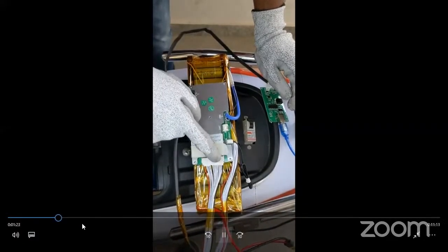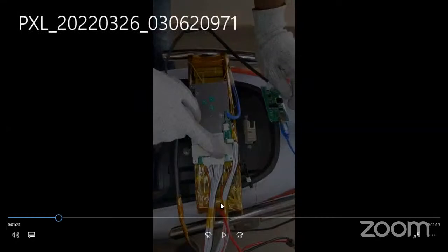It starts from the negative wire. So I'll just take a glance again. You can see the wire goes from B minus to the negative part. Then the B0 wire, which is negative, should go again to the same negative terminal, the first terminal. Then you can visualize that the series wires are going and getting joined at each series, right? Series 1, 2, 3. The white wires are going and joined at the end of the series, right?